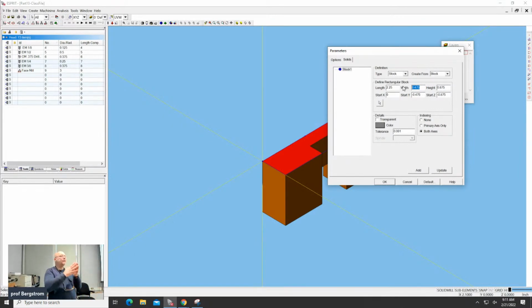That's because the first thing with doing the stock material is you need to define the stock material in the CAM software with exactly the same size and shape as it actually is going to be in the machine. That lets you do the programming and lets you see if it's going to crash when it's doing the operations. All right, so it's 4.475 in width and 0.875 tall. Okay, and you shifted it down minus 0.875.